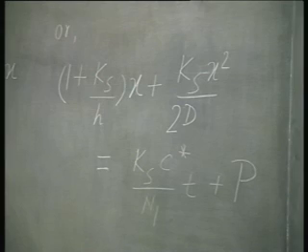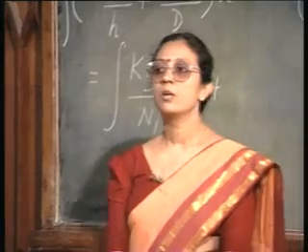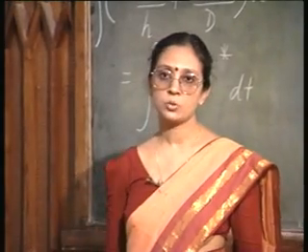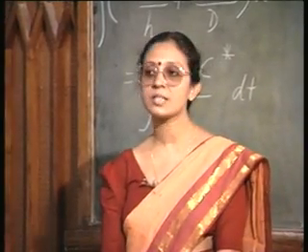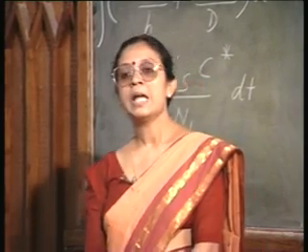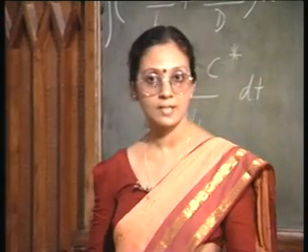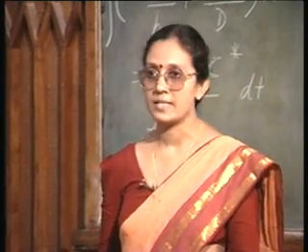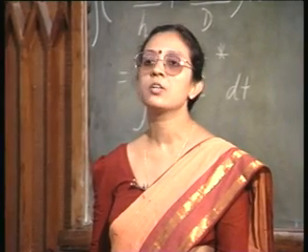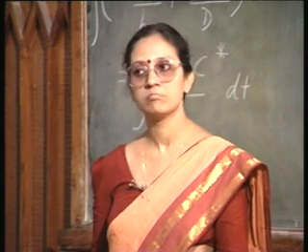And in order to evaluate this integration constant, I must focus our attention to the initial condition, that is at the beginning of time. In a general case, I can say that when the oxidation started, let us assume that the silicon already had an initial oxide thickness present on it.